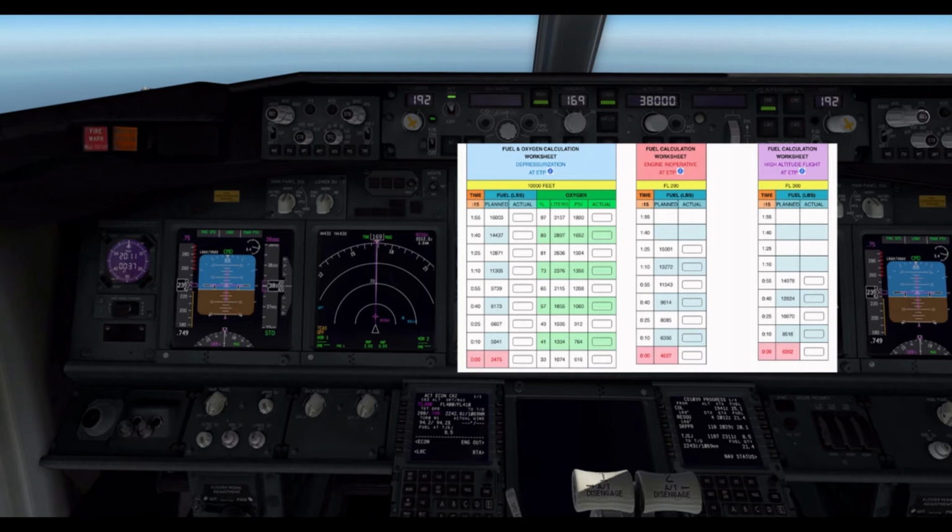The next column in dark blue is what we refer to as a fuel ladder. It's split into two columns, planned and actual. The first row is the fuel remaining, and in each subsequent row, the amount of fuel is reduced by 15 minutes of fuel consumption, calculated by your flight plan and agency. The next column over is a section to record the actual fuel remaining to evaluate fuel reserves, in the same fashion that you would on a normal flight plan.